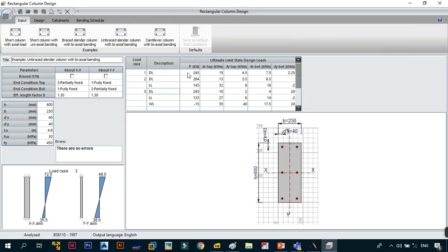Now looking at the loads themselves, we need to look at this column where you have P. So P is the actual force, and just remember, positive means it's a compressive force and negative means it's a tension force. Personally, I don't know why you would have your dead load or live load as tension, or even want to design a column that will be under tension, because let's face it, that's like going to McDonald's, Chicken Inn or Wimpy or KFC and expecting to find a healthy meal.